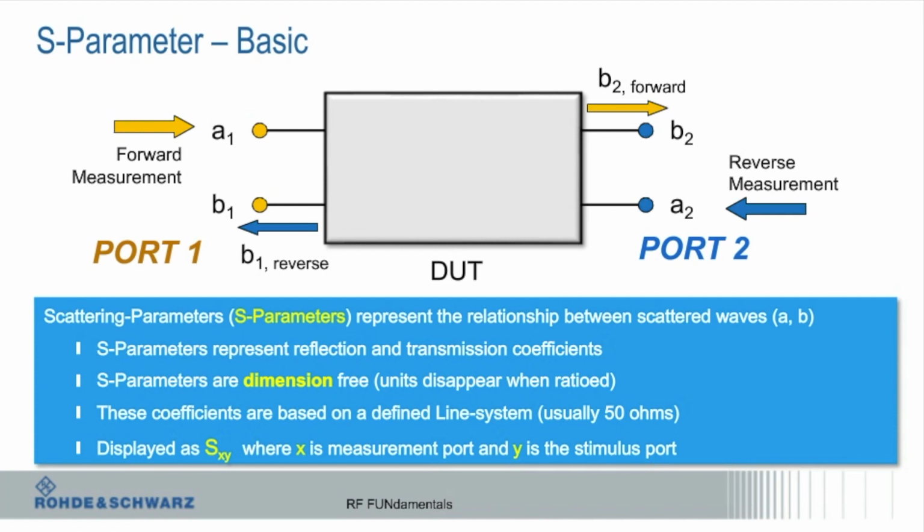Normally with a TDR, I'd be looking at whether that line is 50 ohms all the way along, what the impedance is as a function of distance. The time tells me how far away that mismatch is in terms of length. A VNA can do it with some math. But the tricky thing is, because a VNA mathematically generates that time domain response, it's possible to have a violation of what's called causality. It basically means you're getting a response before you've sent the signal. I know it's kind of odd, but if you're doing that, then talk to me.